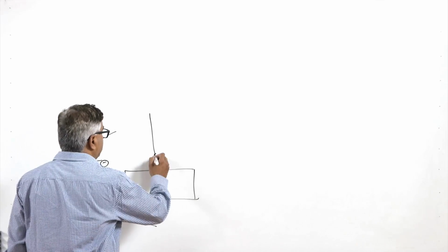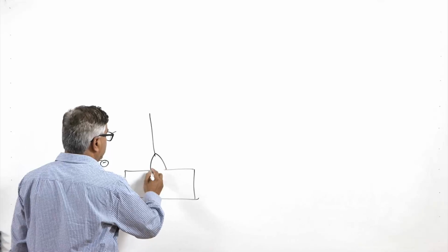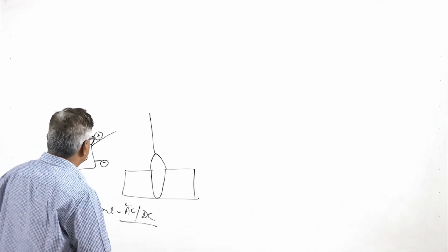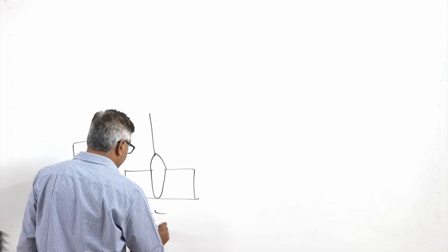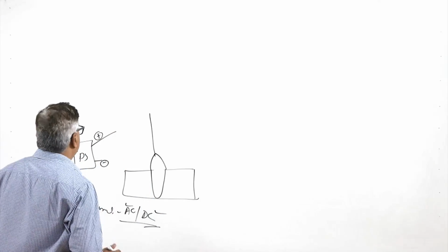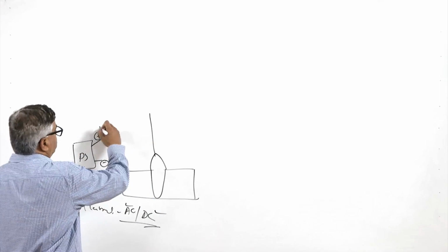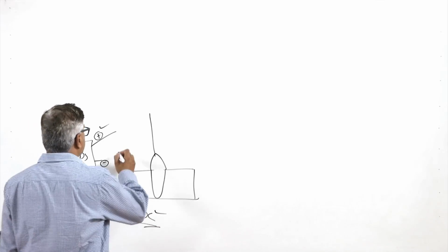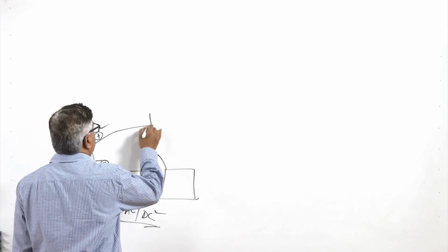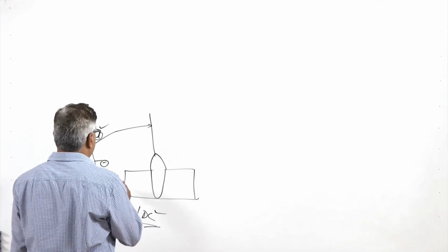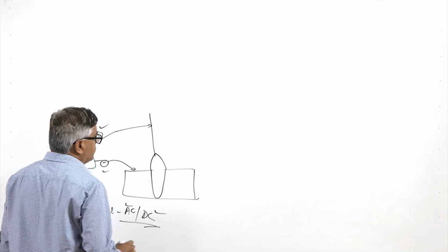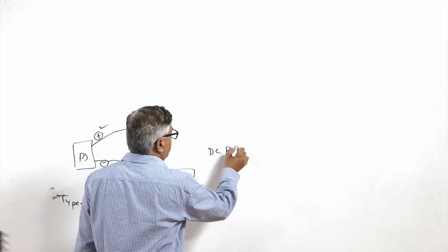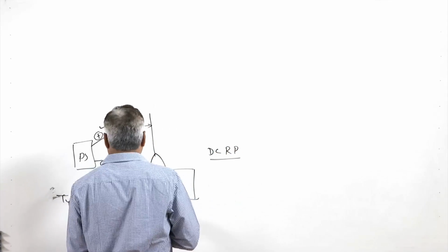Accordingly, the polarity of the welding arc will be changing, while in the case of DC we have the freedom of choosing whether the electrode will be connected to the positive terminal or the negative terminal. When the electrode is connected to the positive terminal and the workpiece to the negative terminal, it is termed DC reverse polarity, or DC EP, electrode positive.